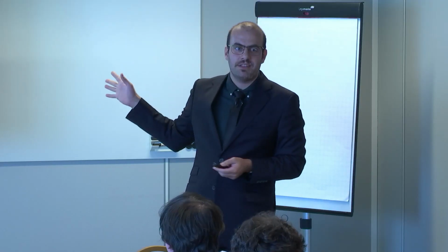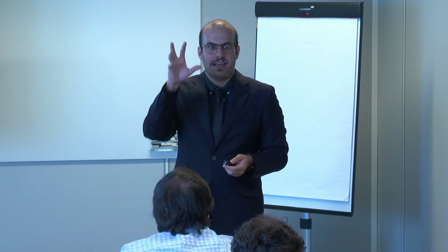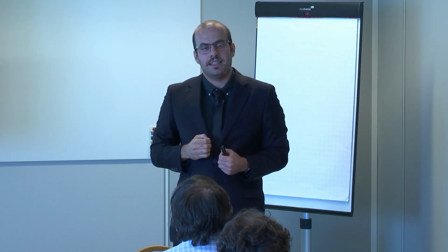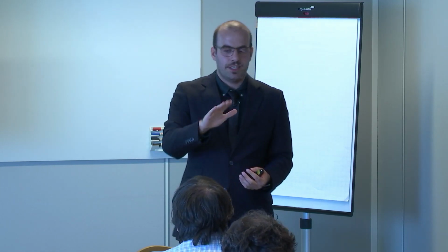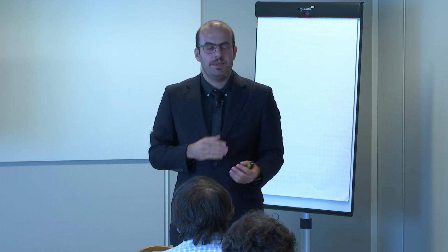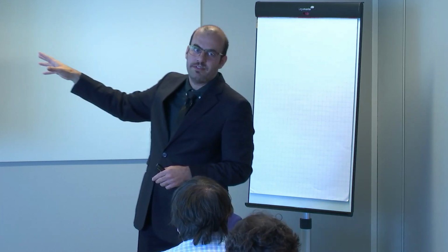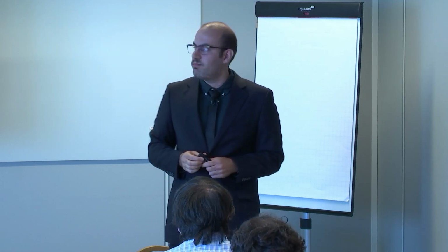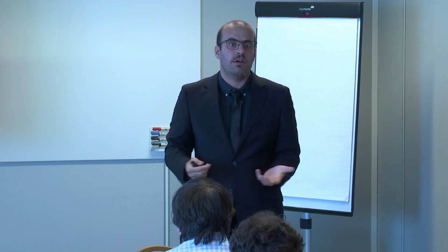Well, that's actually a really good question. The platform that I've used is a TLP, which is surge dominant, and I had a truss emulator at the top of it. I can guess that there might be a relation to the type of platform that we're using here. If we change it to a semi-submersible, which is a little bit pitch dominant, maybe the turbine's effect would show itself in another manner. So I think more platforms need to be studied to have a general hypothesis.